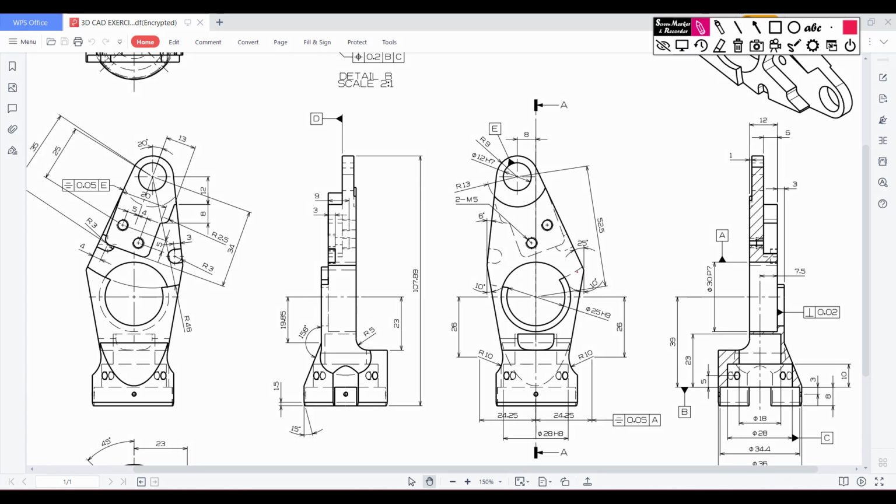First of all, in this back face sketch, we have a circle at the center, and this circle has a dimension of 30 diameter. So I will draw a circle of 30 diameter. From that circle we have another circular profile, a circle with a radius of 9 unit, and its distance is 8 unit here, and it has a distance of 52.5 unit.